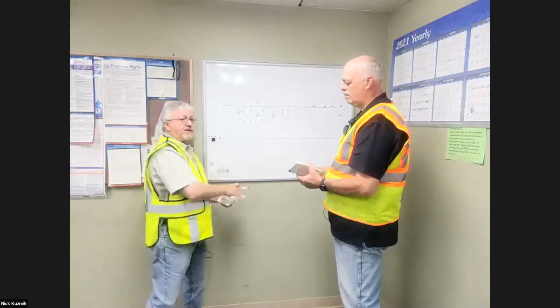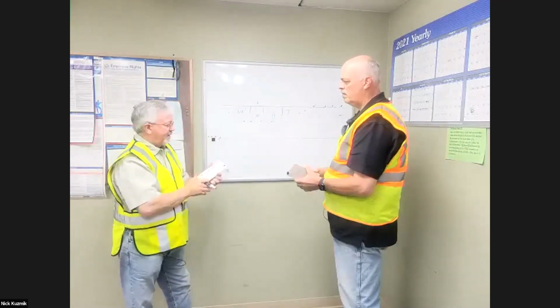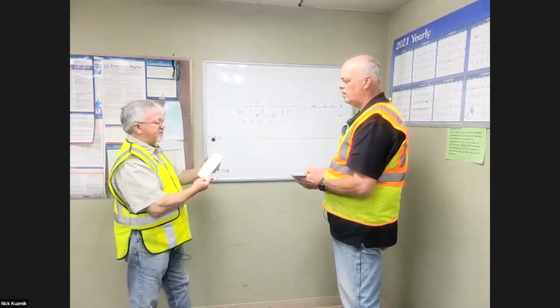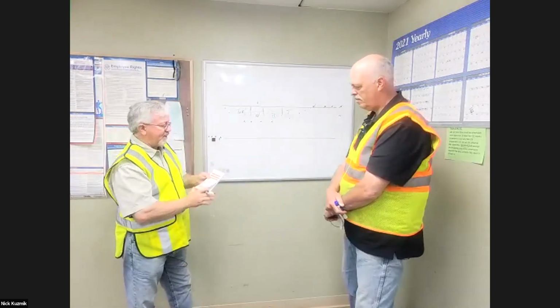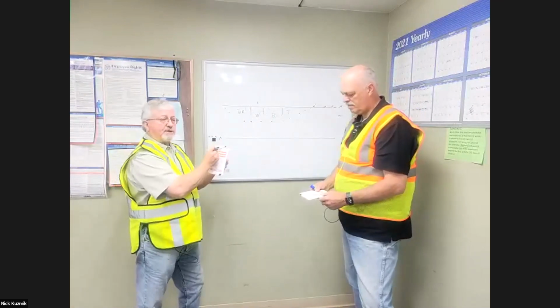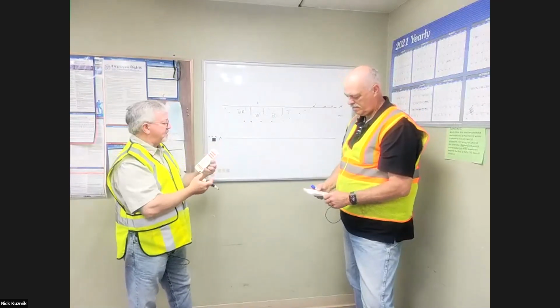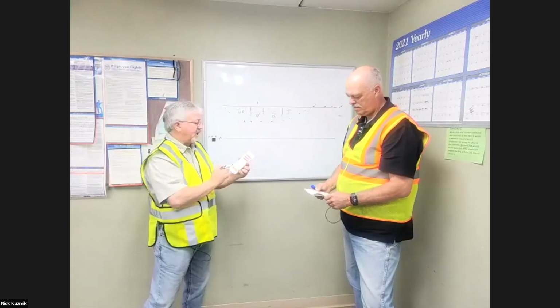These are all set up based on the velocity of the traffic, and all that information is in here. There are formulas for the taper zone. There's also a table in here that'll give you an idea how far you need to set that up, where the spacing is based on the velocity of the traffic.